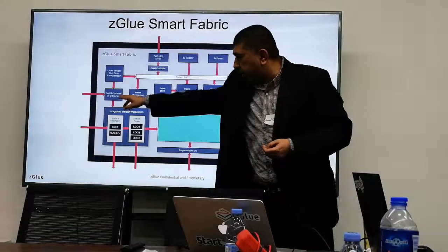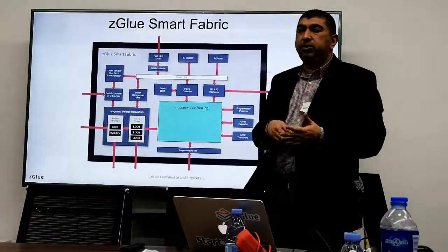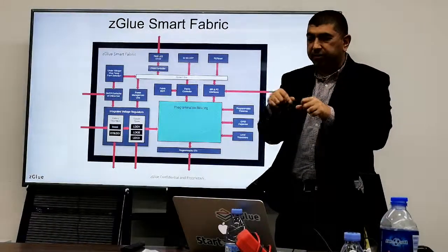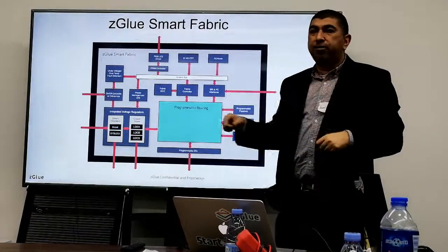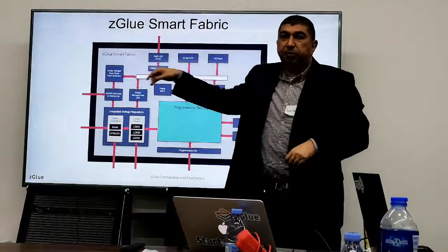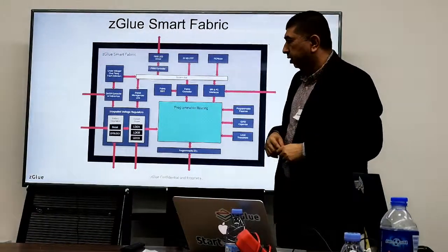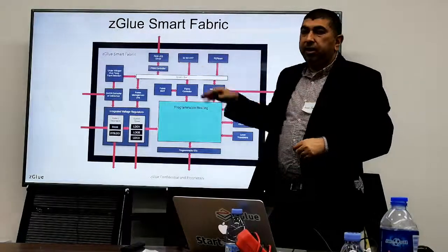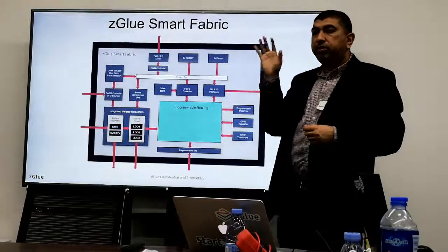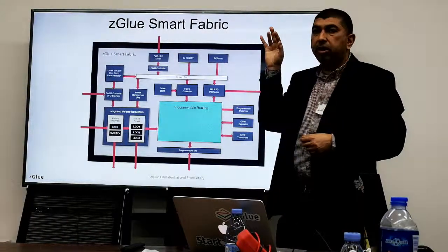Now look at this one. There are on-off controllers with switch debouncers. A lot of these devices, you need a little button. You want to press a button to turn it on and off. That circuitry is built in with different timer options that you can select. It also has, like we said, LED drivers, which can control the color of the LED.